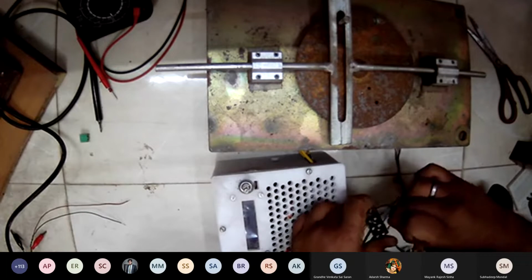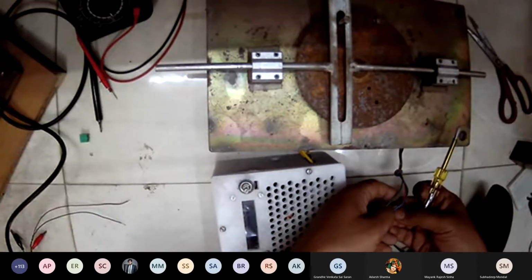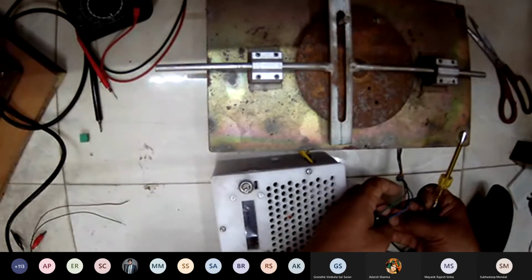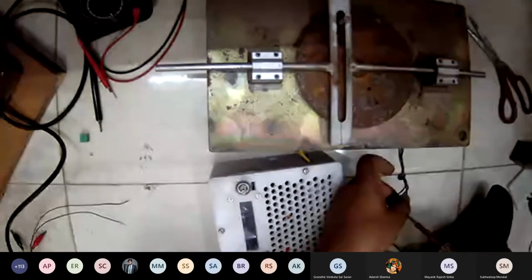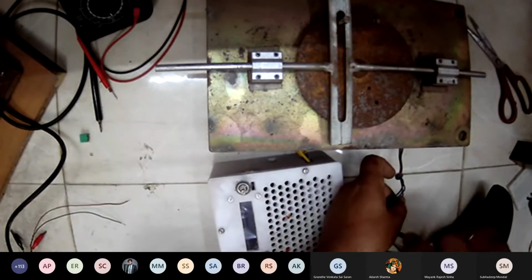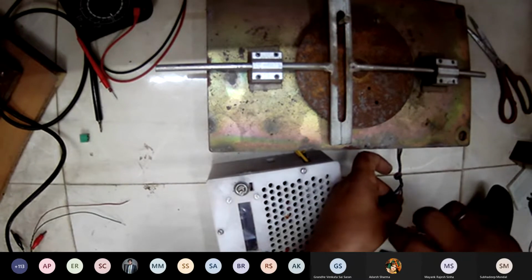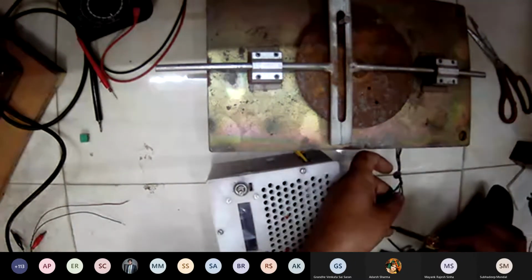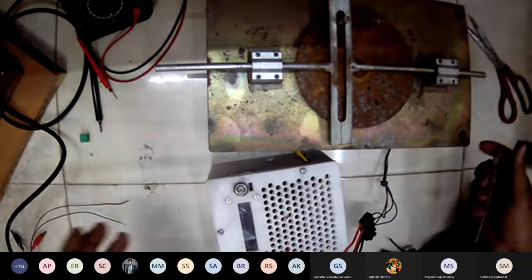If that doubt is there, you can always use a shaft encoder, which is sold as a servo stepper motor. That servo mechanism tries to always compensate for it. If it misses a step, it will try to provide more current to the coil so that it can do that step.